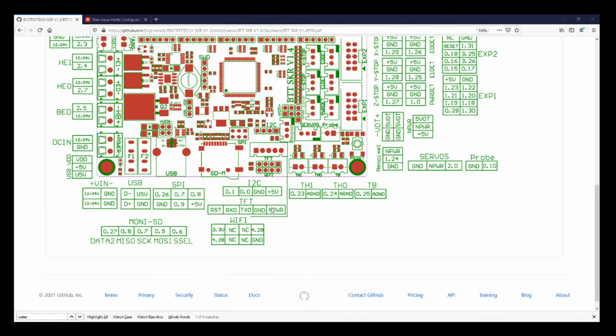So here's the multimeter. Sorry, it's kind of difficult to fit everything in here. So I'm going to click here, and I'm going to measure this pin. Not that one. I'm going to measure this pin. Not that one. Looks like that's 5 volts. That's half a volt. So the voltage is coming in right here.